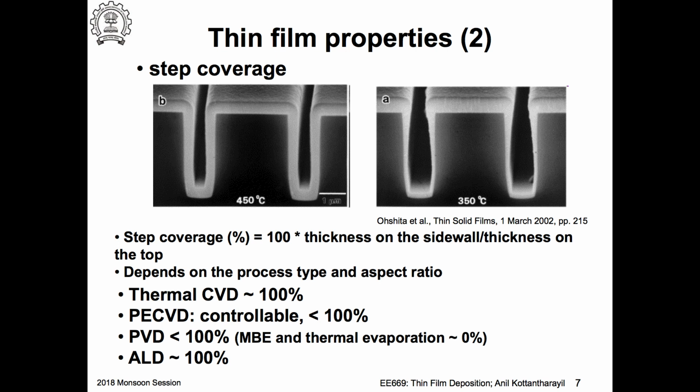What difference do you see? The thickness on the sides is not the same as the top. Here, these two thicknesses are closer. So this is what is referred to as step coverage. We'll formally define it. Now, what is the problem?